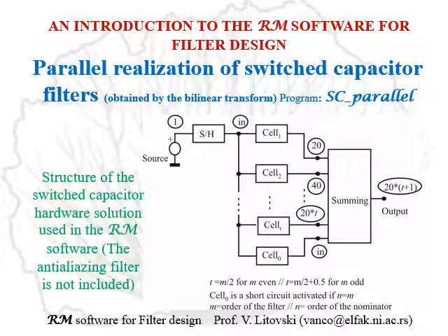Due to the presence of switching, the output signal is full of sharp changes or harmonics. So for the filter to be completed, one needs the so-called anti-aliasing filter to be added at the output, which is not shown here.